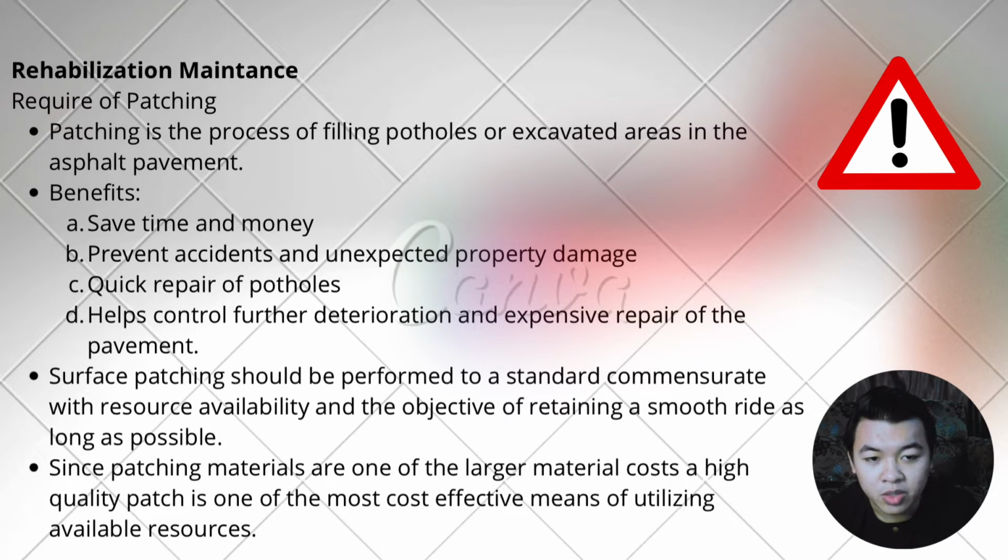Surface patching should be performed to a standard commensurate with resource availability and the objective of retaining a smooth ride as long as possible. Other than that, patching material is one of the largest material costs. A high-quality patch is one of the most cost-effective means of utilizing available resources.